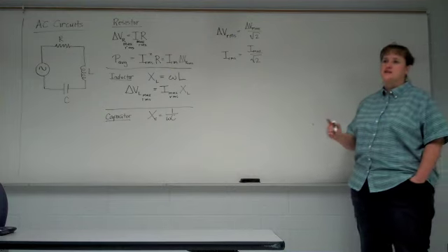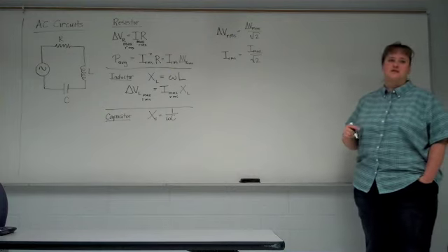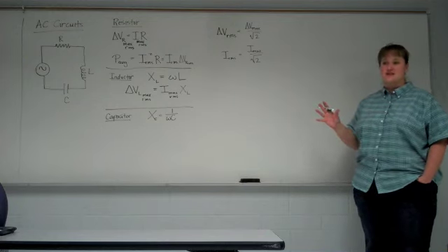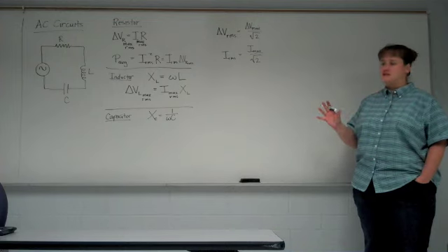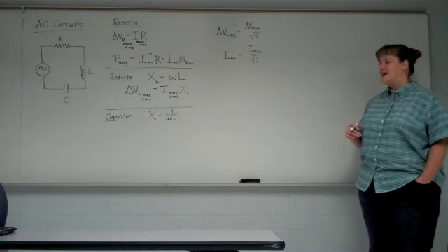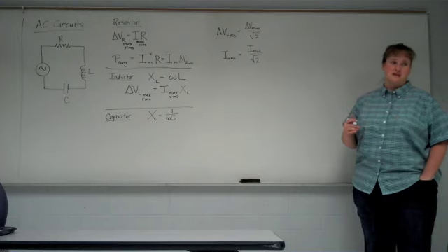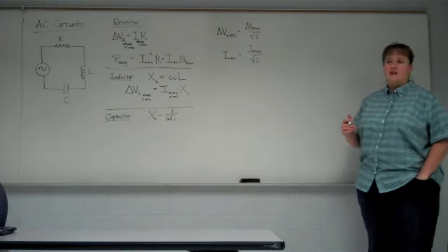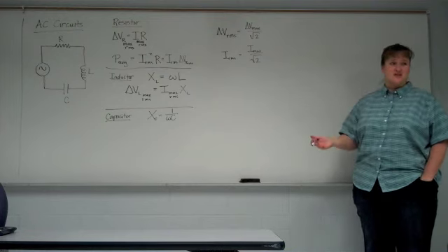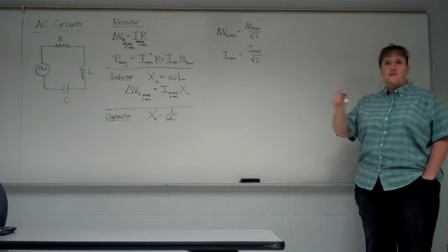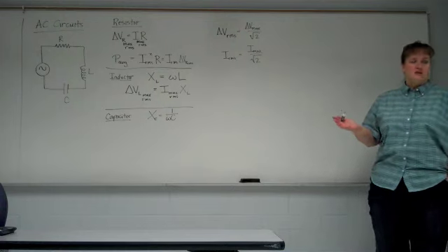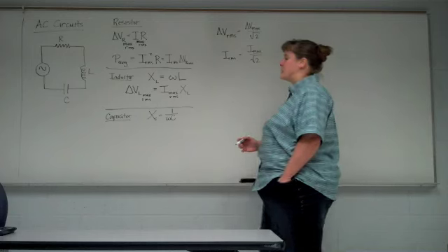So the capacitor and the inductor are opposite of each other. If frequency is high, the inductor has a really high resistance in the circuit, and it acts as if it were an open circuit. A capacitor, if the frequency is really high, the X sub C is very small, and it acts almost as if it were a short. If you think about it, the capacitor is going to be trying to charge up and discharge. If the current is flip-flopping too quickly, the capacitor is not going to have time to charge up at all. And so that's why X_C gets smaller.